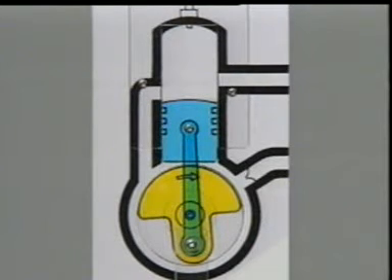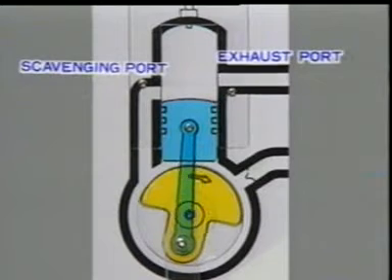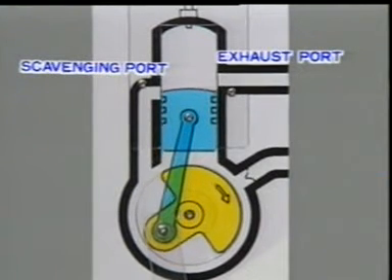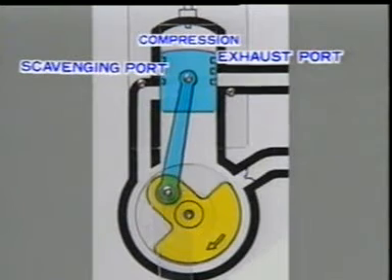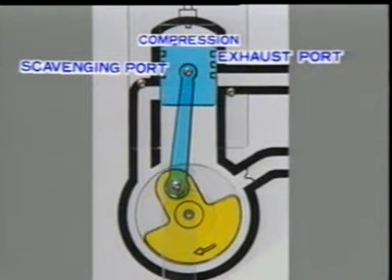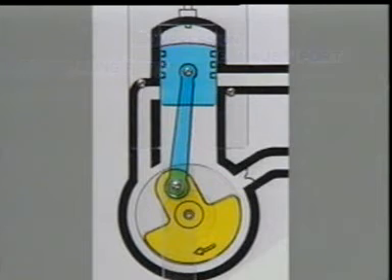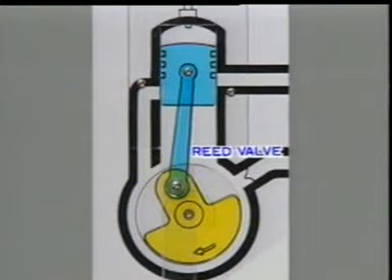First, as the piston passes BDC, it begins to rise. The scavenger and exhaust ports are closed in succession and the mixture in the cylinder is compressed. At the same time, because the vacuum in the crankcase chamber is increased as the piston rises, the reed valve opens in response, and the mixture is taken in to the crankcase chamber.